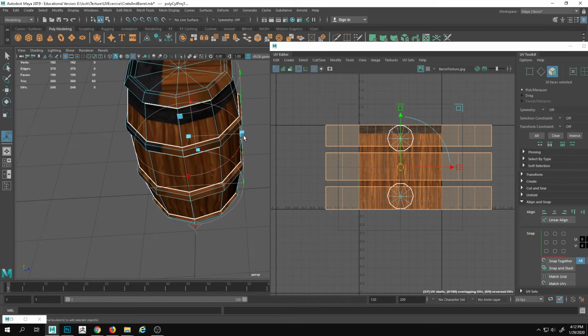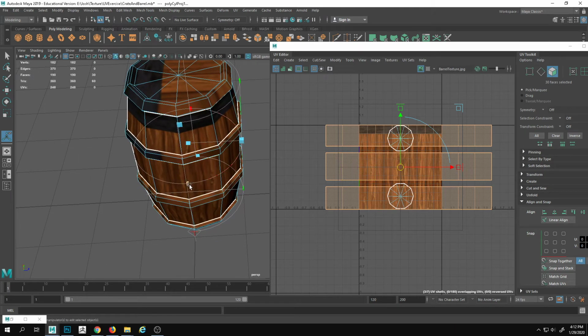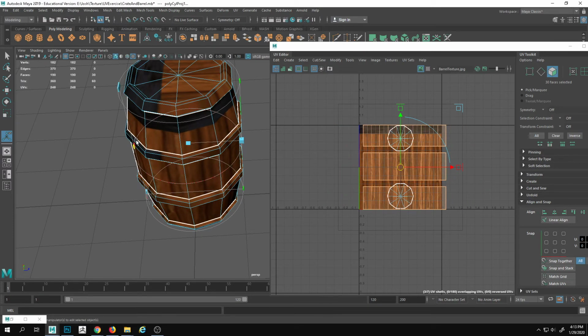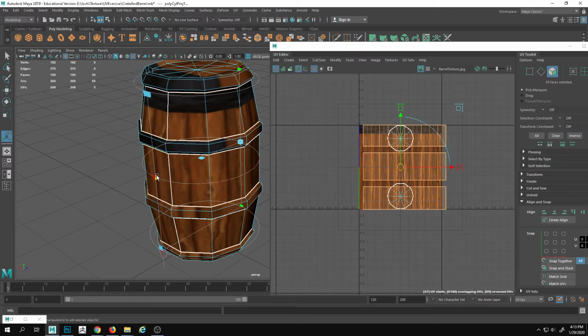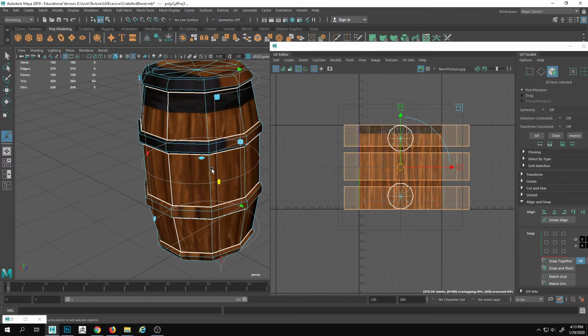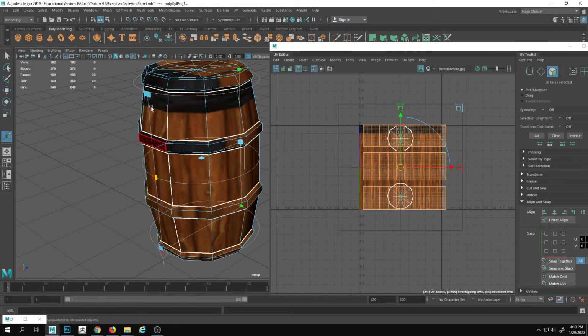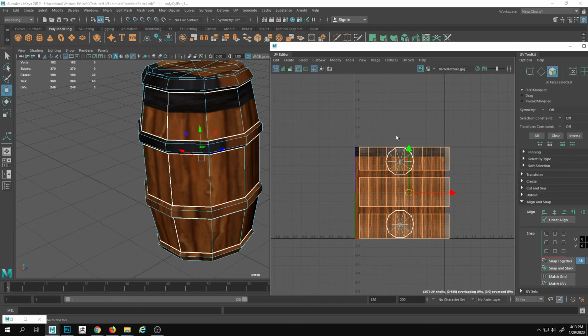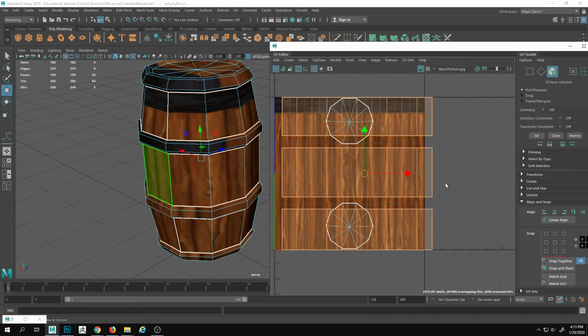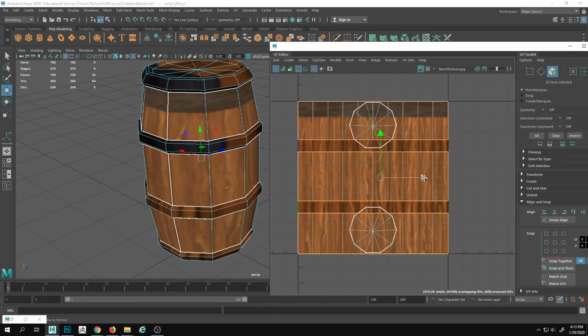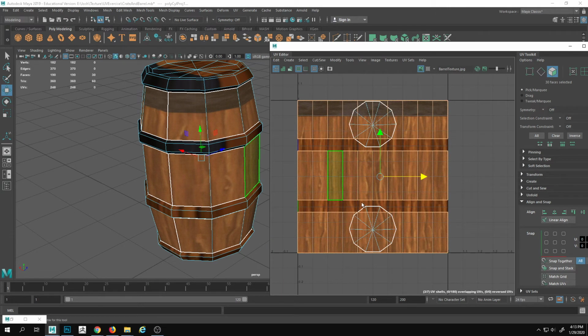What that allows for me to do for a cylindrical unwrap is I could take this, left click and drag. And notice how that's squishing that all the way over. It's actually making that so that cylindrical unwrap is going all the way over from one side to the other. All right, so now that I have that, I can drag this over to fit in the UV space, and I'll clean it up a little bit.